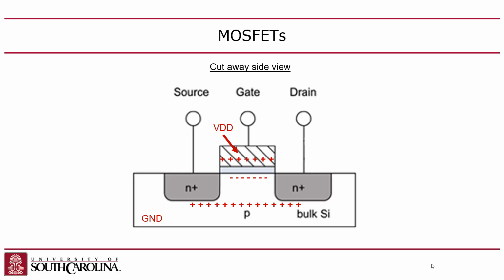that channel, right? Now, why do I bring this up? Why is this important? The problem is when you charge a capacitor, there's two plates on a capacitor, right? And in order to charge a capacitor, there has to be a voltage difference between the two plates, right? So if this is the first plate and this is the second plate, I know what the voltage of this top plate is because that's the gate. I'm driving that with a signal of some kind, right? But what is the voltage of the channel? I mean, it's not ground because, as I mentioned, it's disconnected from the ground, right?